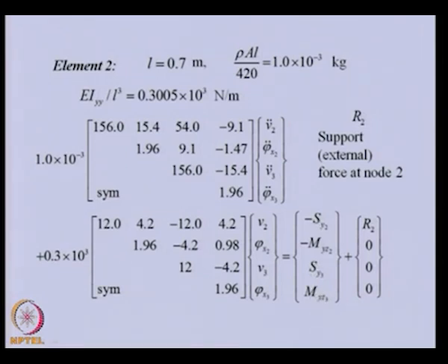Apart from this, because once we take out the shaft from the support, there will be a reaction from the bearing. This reaction from the bearing and this particular shear force are different. This is coming because we have cut the shaft into two pieces, that is why it is coming.